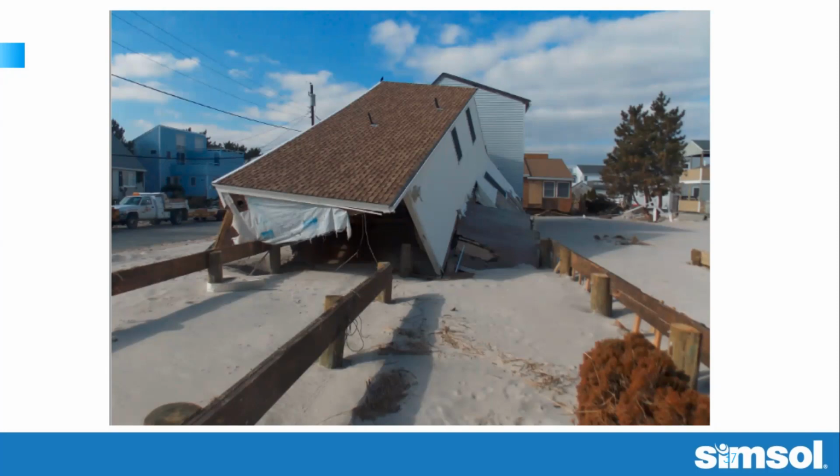And you can notice too, in the left side of the photograph, you see a piece of debris wrapped around one of the piers there. That may or may not be related to water or wind. I mean, again, this is about a week after the storm, so it's hard to use something like that. But the fact that the building is displaced in a manner that is consistent with where the surge would come from, and the fact that we have very little roof damage, this is definitely a flood event.